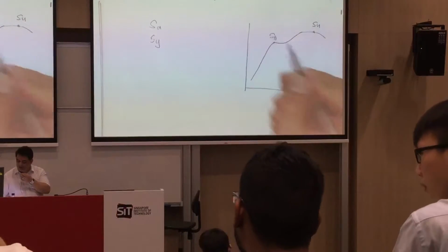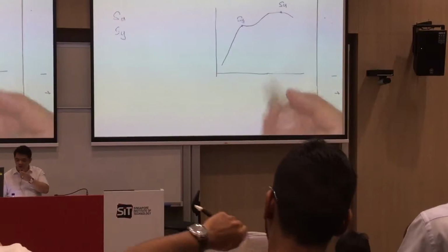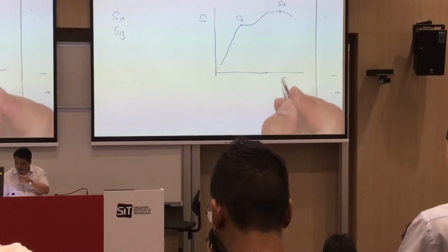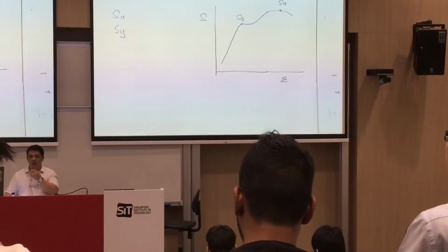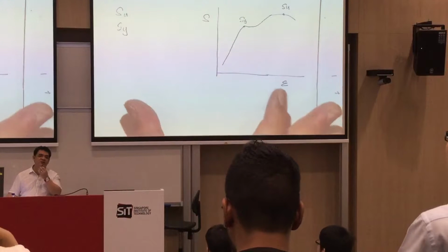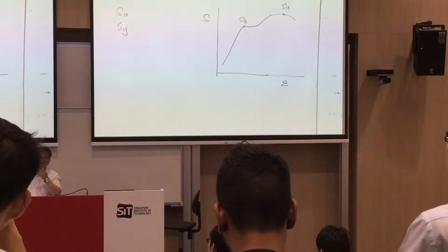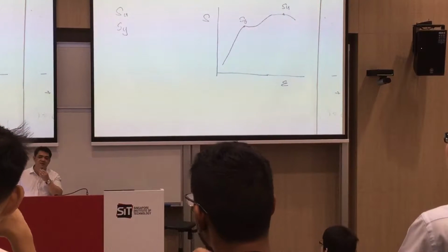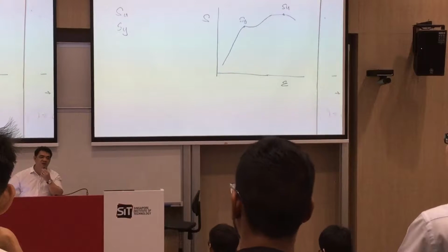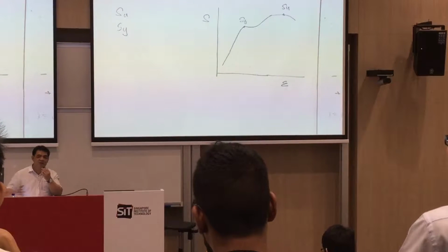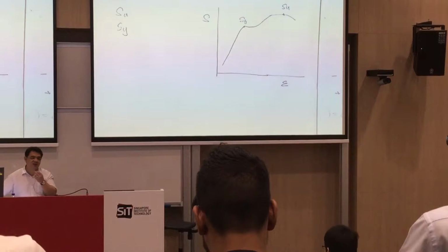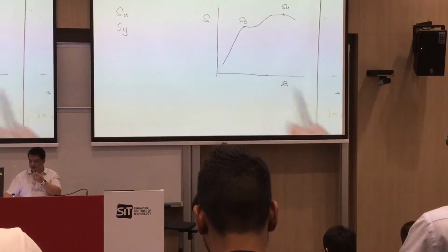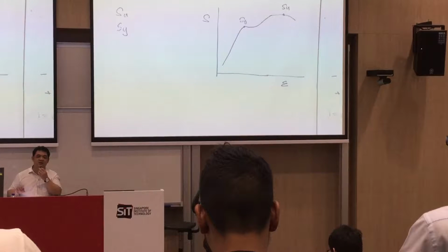This one will be your yield. So this one will be your stress strain curve. So again, where do you get this one? You don't get this one from analysis. You get this one from testing. The tensile testing that I've just shown you, or probably have done that in Polytechnique, right? Tensile testing. So from there you will be able to get your stress strain curve.